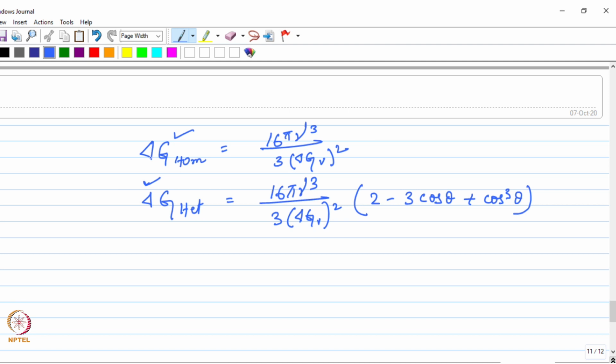So that is how you get a higher nucleation rate in the case of heterogeneous nucleation, and the higher the nucleation rate, the lower will be the grain size. That is how heterogeneous nucleation leads to a finer grain size in the solidified material.